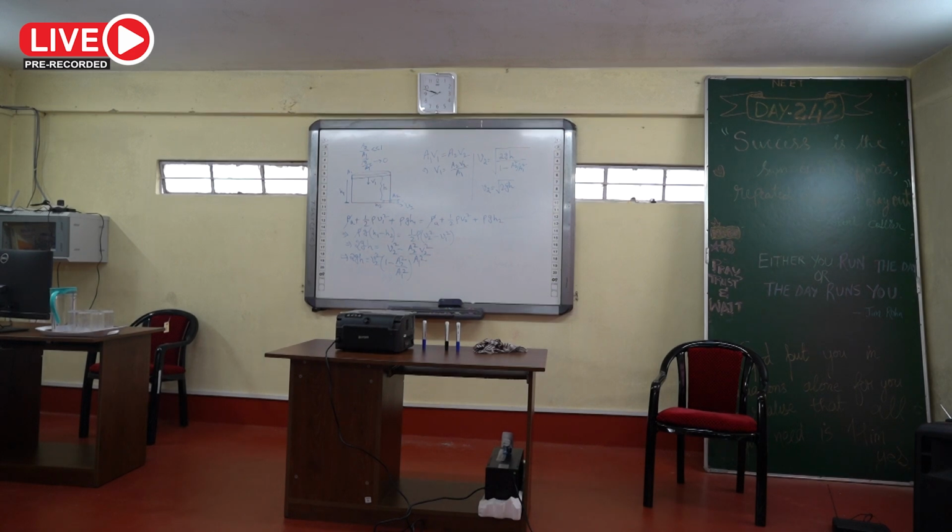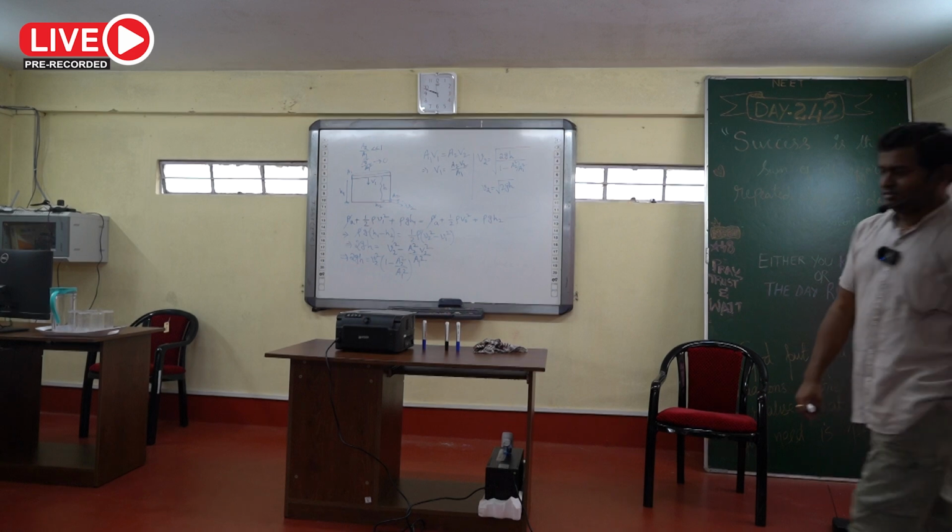For A2 to give efflux, what do we have to do? A2 should be very very less than A1. Otherwise there will be no efflux. What does efflux mean? Tank is filled and now from the bottom portion there is a pinhole. Suddenly the pinhole mouth is open. Water is rushing with a high speed. That is called efflux.